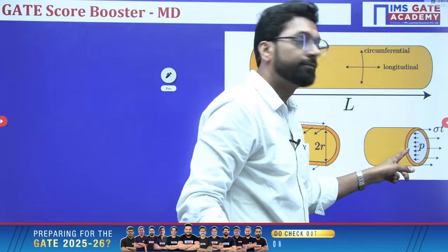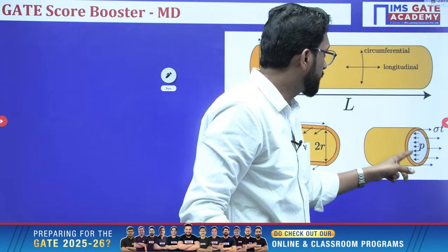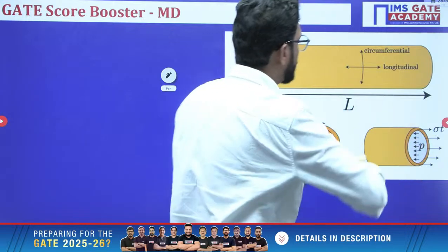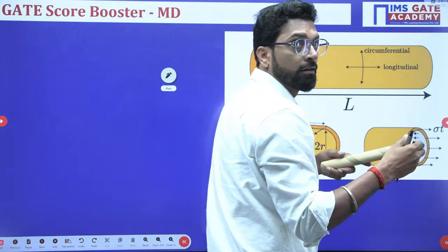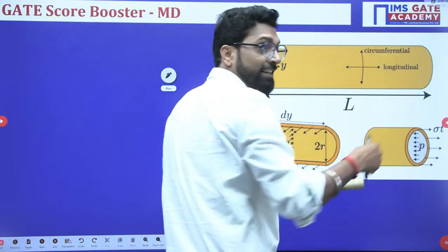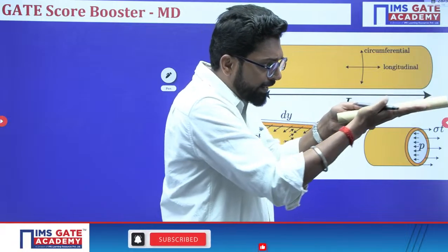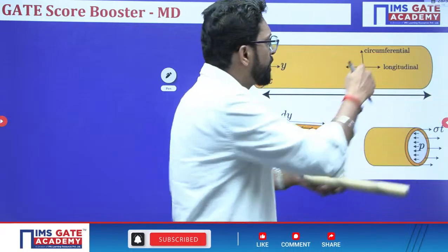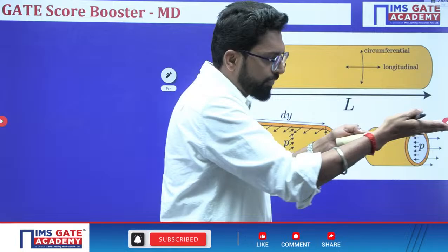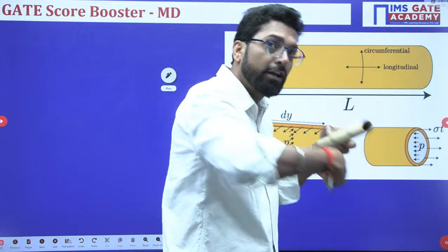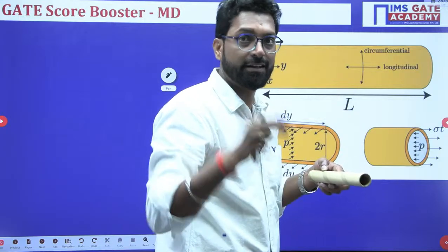And if this was circumferential stress, the cylinder will fail along the axis. Longitudinal stress, the cylinder will fail along the circumference. That is a little bit of theory.